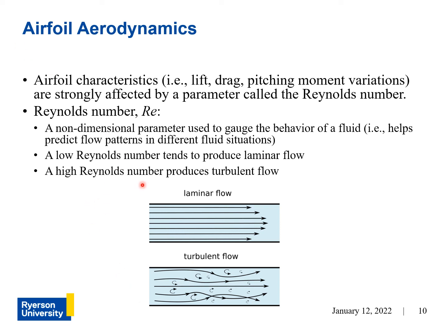And as you'll see later, when we compare different airfoil shapes at different Reynolds numbers, the Reynolds number will greatly affect the drag coefficient of an airfoil. So that's why if you want your glider to fly a little further, knowing the Reynolds number would be helpful.